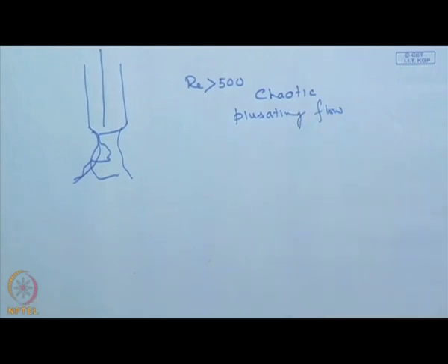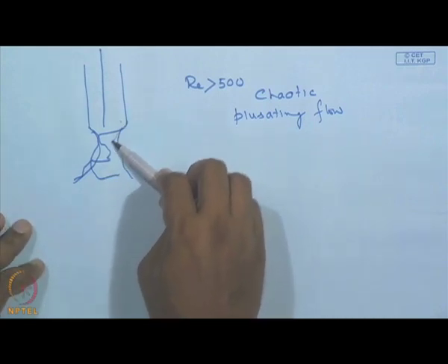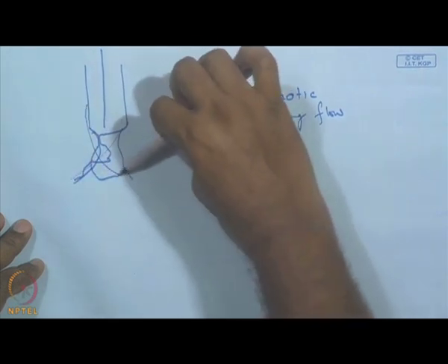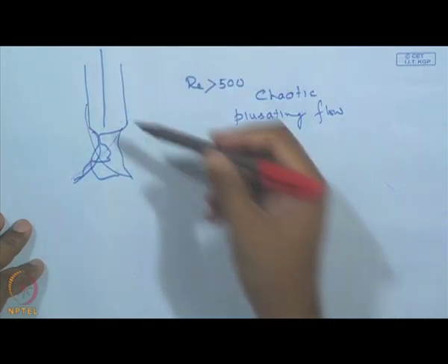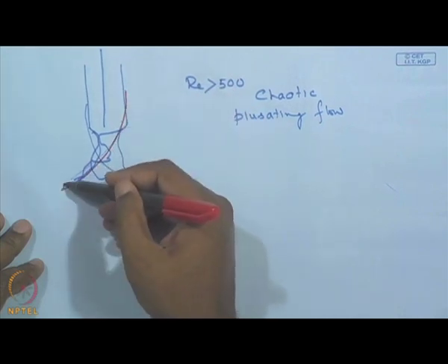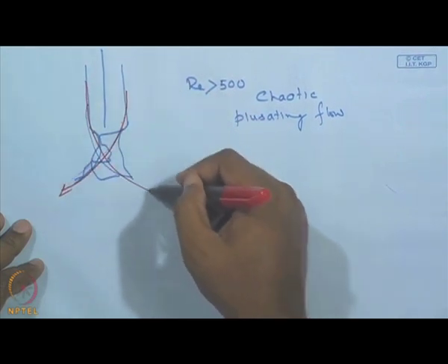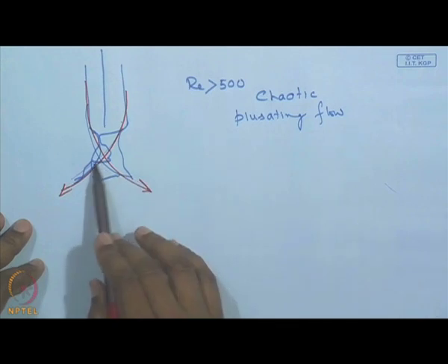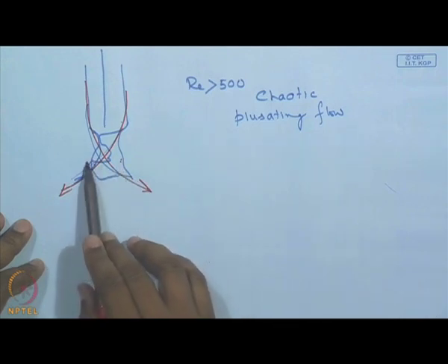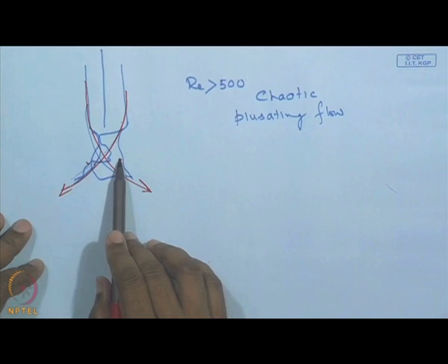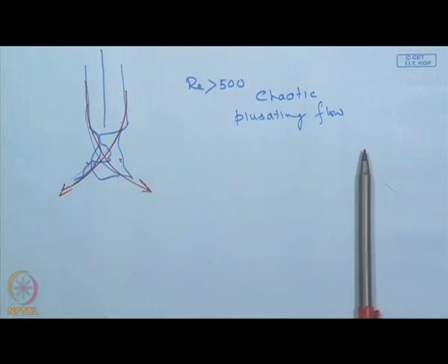The vortex breaks down and you get single flashes of fluid swaps to the other side. So, liquid 2 will move to this side, liquid 1 will move to the other side, and this takes place at such a high pulsation that the mixing quality may actually decrease.